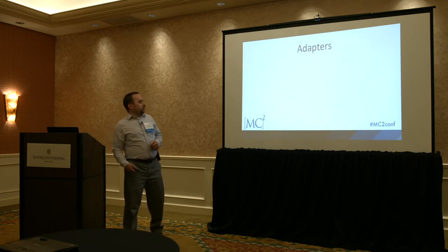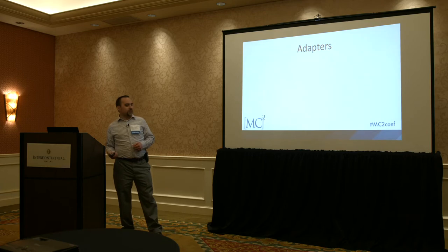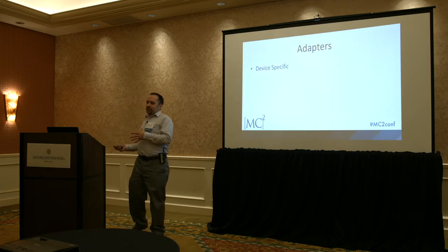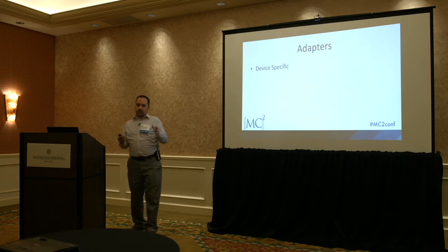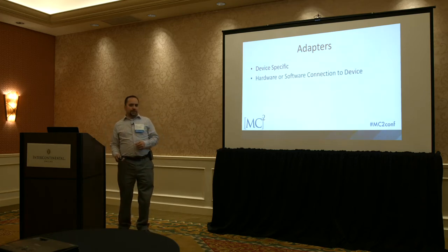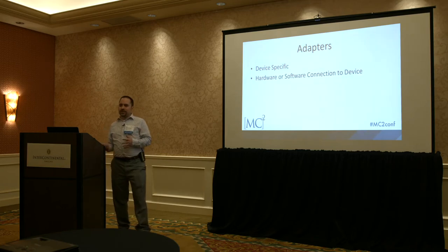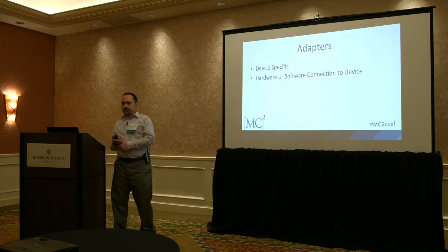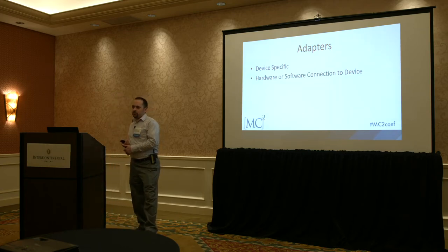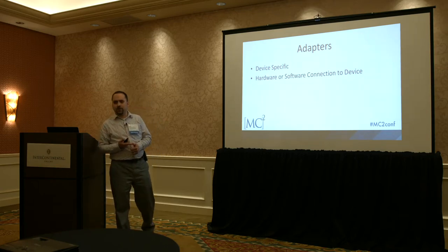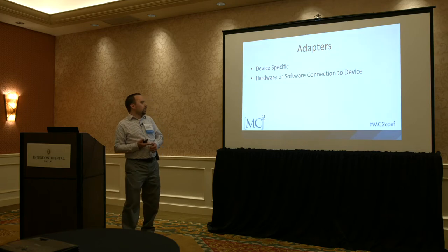So then we bring adapters into the chain. And adapters are meant to be device-specific and speak the language of the devices they're written for. And there's all kinds of ways they can connect. They can do a hardware connection with DIOs. We see a lot of that on legacy machine tools, or say if you're connecting to sensors or something like that, you're going to have a hardware connection to your adapter.